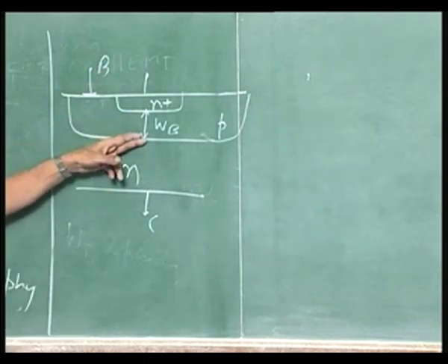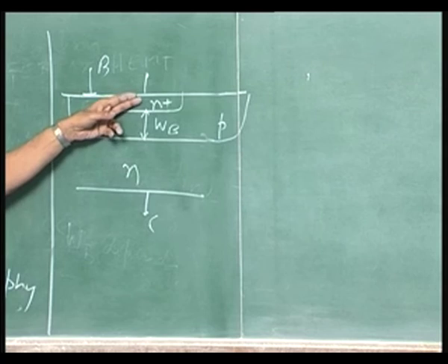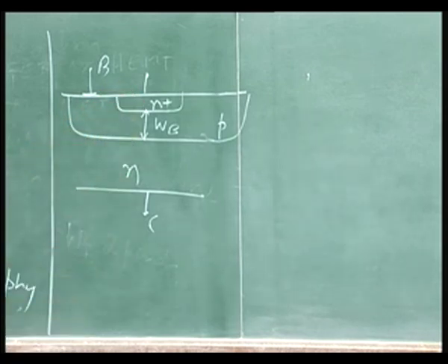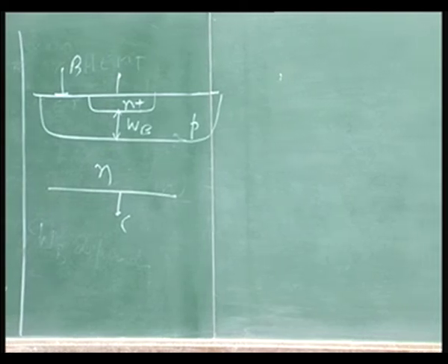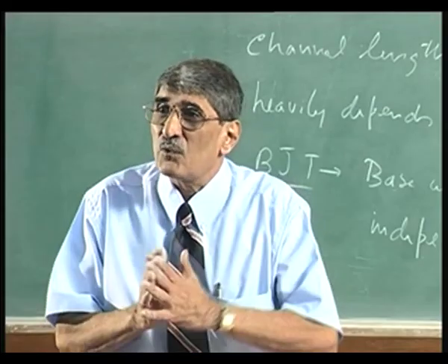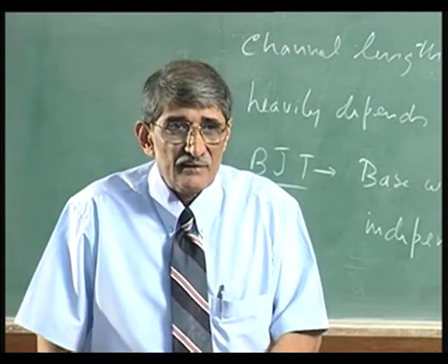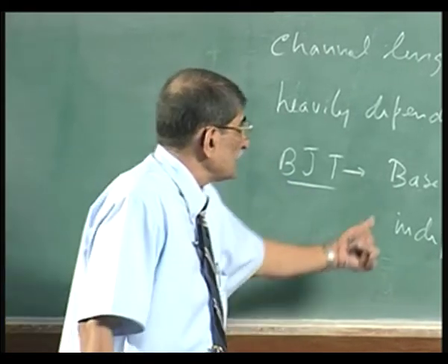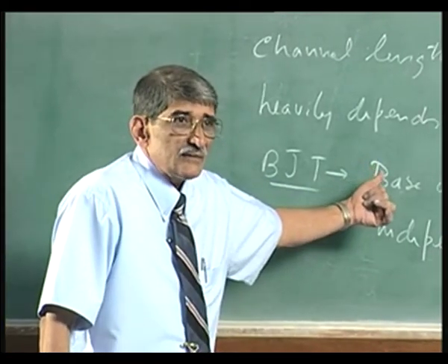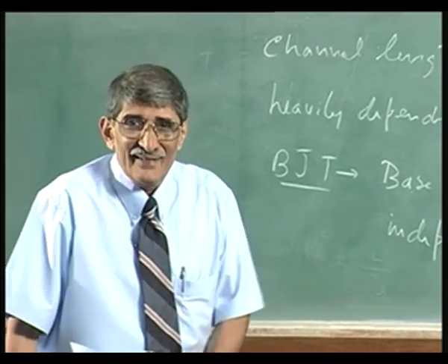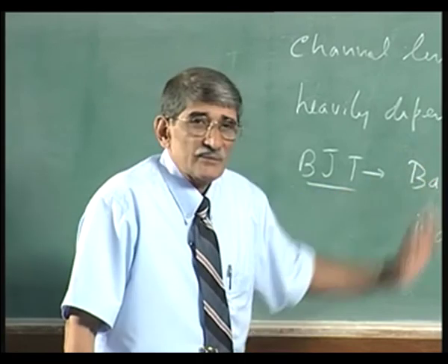or you can implant this region, get the junction. So, this base width you can control precisely by the process, not by lithography. You do not have to depend upon lithography. That is where actually the bipolar scored in speed in the 70s, but it stayed on. Even today it competes with that, because if you do not have high-end lithography, you can depend upon that.